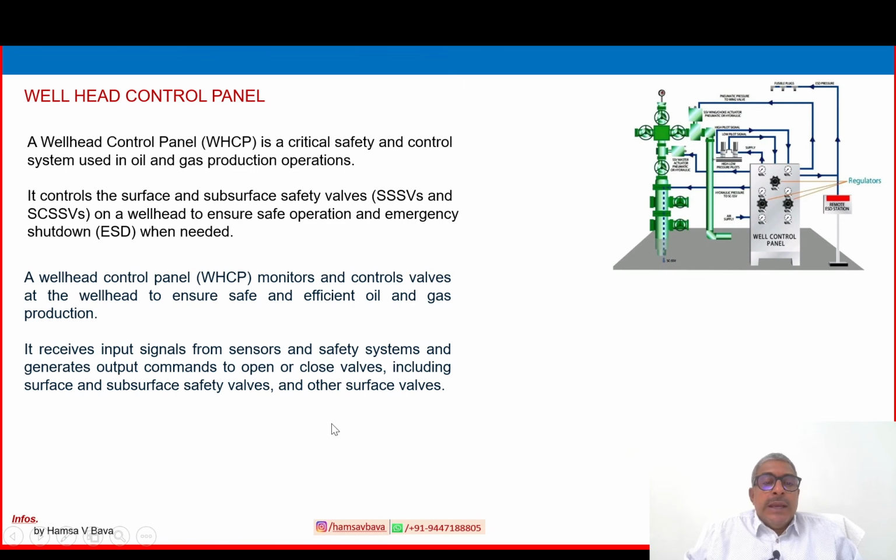Sensors and safety systems generate output commands to open or close valves, including surface and subsurface safety valves and other surface valves. So a number of valves are linked with this safety system, the ESD system, this logic system that will activate automatically in the event of an emergency or hazardous condition.